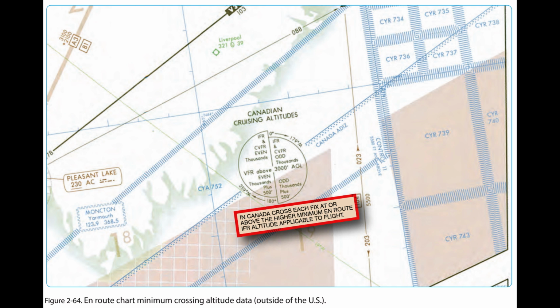If no applicable minimum altitude is prescribed in 14 CFR Parts 95 or 97, the following MIA applies: in designated mountainous areas, 2,000 feet above the highest obstacle within a horizontal distance of 4 nm from the course to be flown, or other than mountainous areas, 1,000 feet above the highest obstacle within a horizontal distance of 4 nm from the course to be flown, or as otherwise authorized by the administrator or assigned by ATC. MIAs are not flight checked for communication.